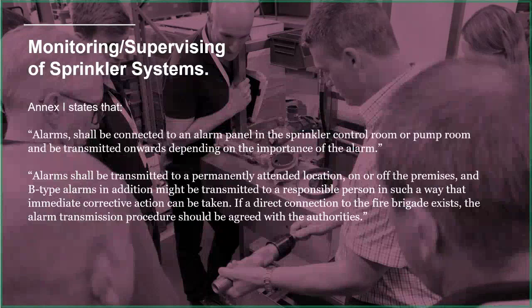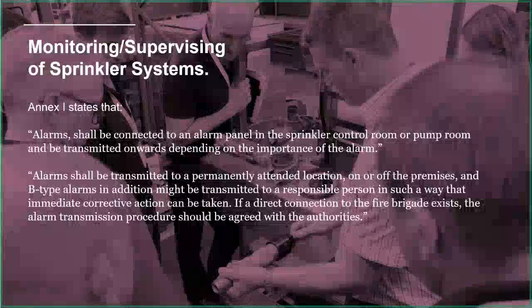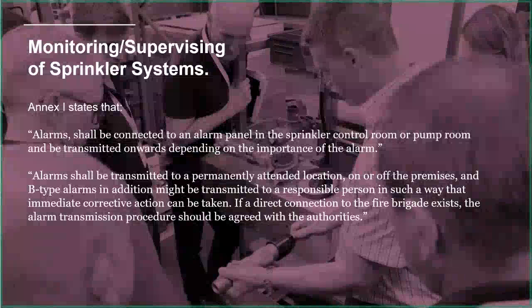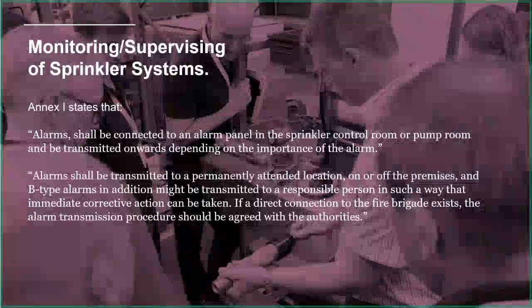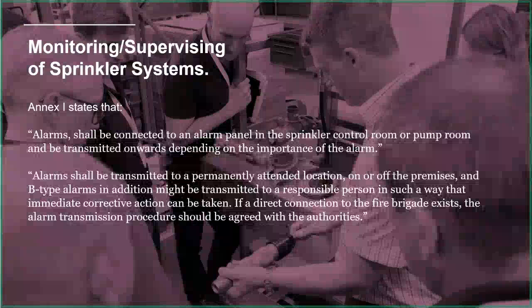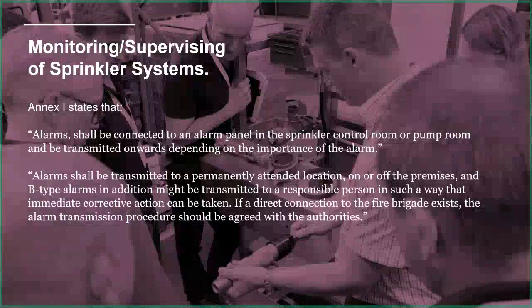A couple of other quotes here from Annex I. So Annex I is kind of going into the specifics of what each alarm needs to do. It says alarms should be connected to an alarm panel in the sprinkler control room or pump room and be transmitted onwards depending on the importance of the alarm. So again, for me, I suppose that's a little bit loose in terms of what exactly we need to do. But important alarms, I would say type A alarms, need to be passed on to other systems appropriate to the building.